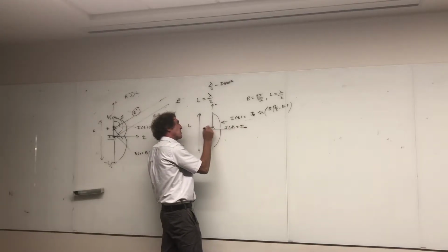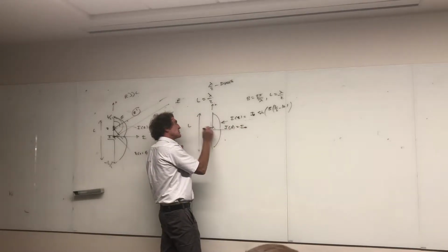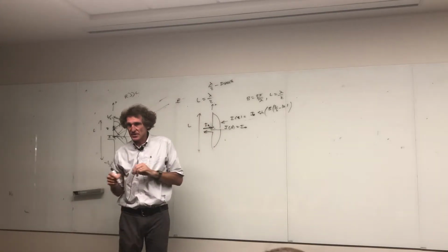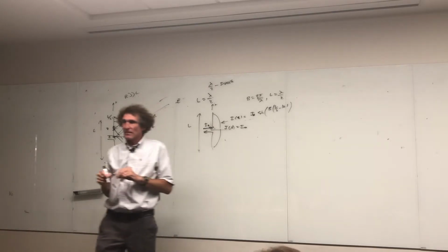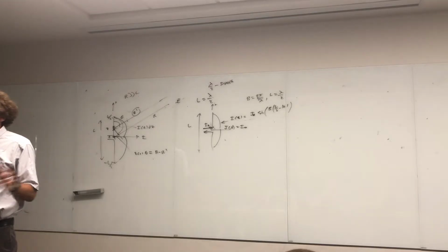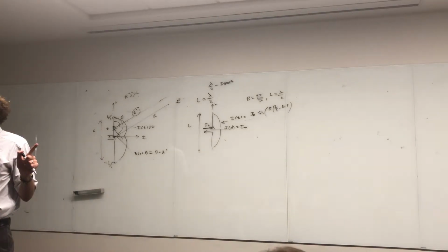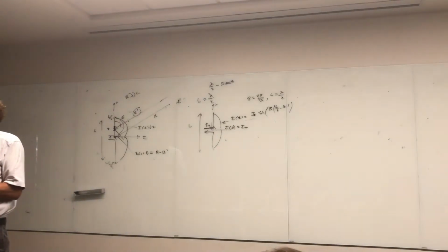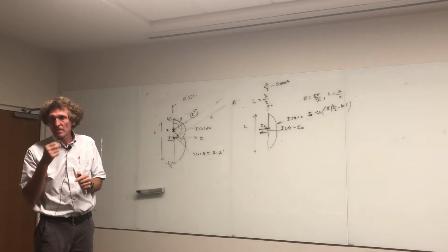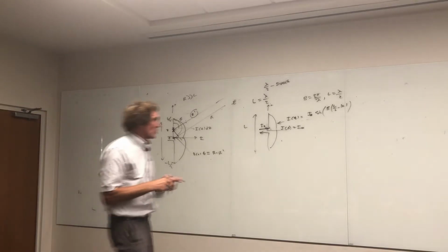This current flowing in, this current flowing out, is differentially driven, I naught. That's the first thing you have to notice. So we're going to have a peak current fed to the antenna at that point. And it would be peak for anything shorter than that too. For lambda over 2 on down to the shortest of the short dipoles, you're feeding at the peak current level. Are you with me? Now, that's important.